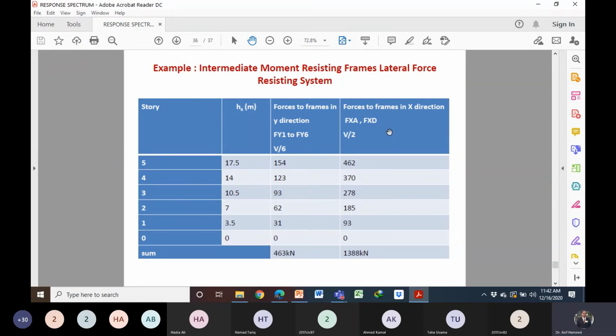अभी हमने क्या किया है? By using the horizontal distribution formula, we have distributed the forces horizontally in the different frames, and once we have the base shear in each frame, we can again distribute vertically in that particular frame by using the same formula. हमने horizontally distribute किया है each frame में, फिर vertically distribute किया, वही formula use किया हमने जो पहले use किया था. Any question? क्लियर है ना? उसमें हमने पूरी बिल्डिंग में किया था पहले, ठीक है ना? सेंटर ऑफ स्टिफनेस में हमने अप्लाई की फोर्सेस. अगर आपने मैन्युअली calculate करना है, if you have to find out the response manually, then definitely you need the forces to be applied along, two dimensional analysis करना है आपने, हर फ्रेम में कितनी आएगी. So first you can distribute the base shear in each frame separately and then you can distribute vertically.